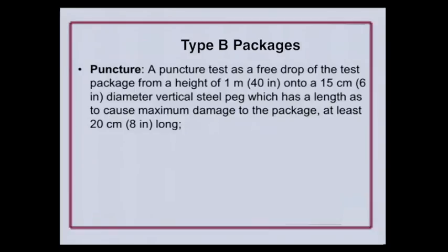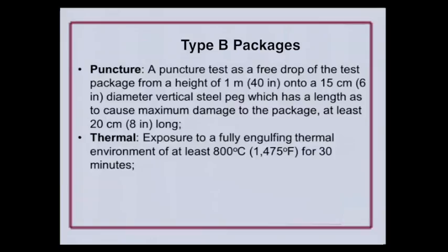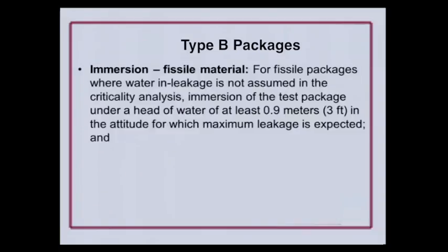And then you have a thermal test. The package is exposed to a fully engulfed thermal environment of at least 1,475 degrees Fahrenheit for 30 minutes. Hypothetical transportation accident, worst case basis. And then we're going to put it in water.